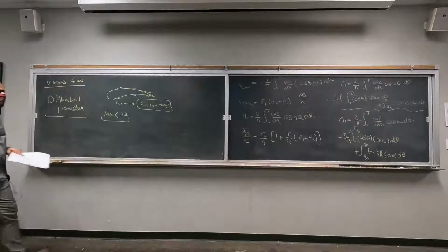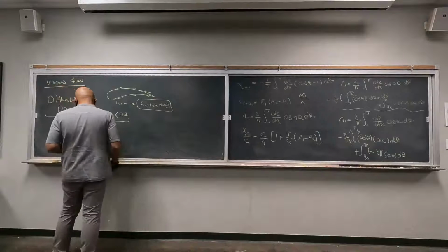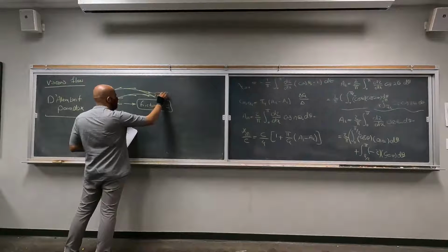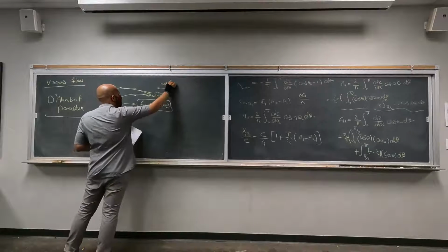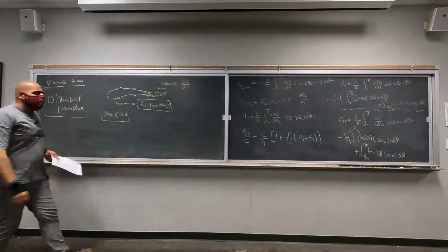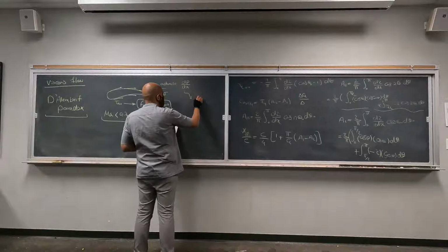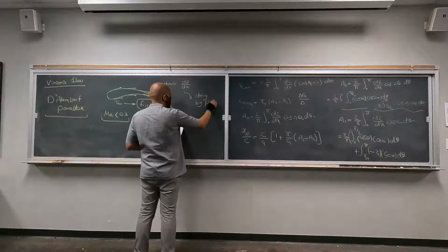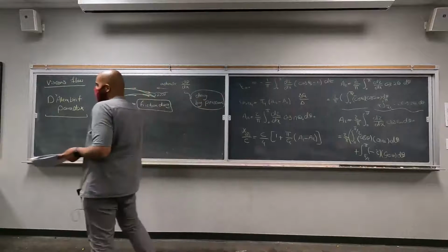Okay? But there is another type of drag that is present here, especially when you have flow separation. I think we talked a little bit about flow separation, right? Which means that you are going to have an adverse pressure gradient. And the drag due to this adverse pressure gradient is called the drag by pressure. Some people call it pressure drag or the form drag. Okay. Two main types of drag.